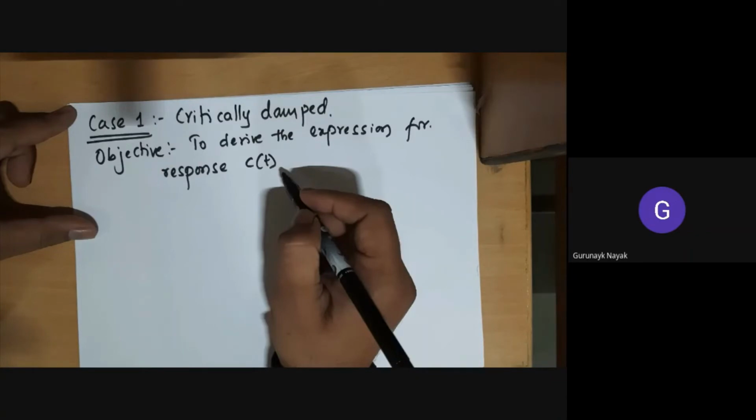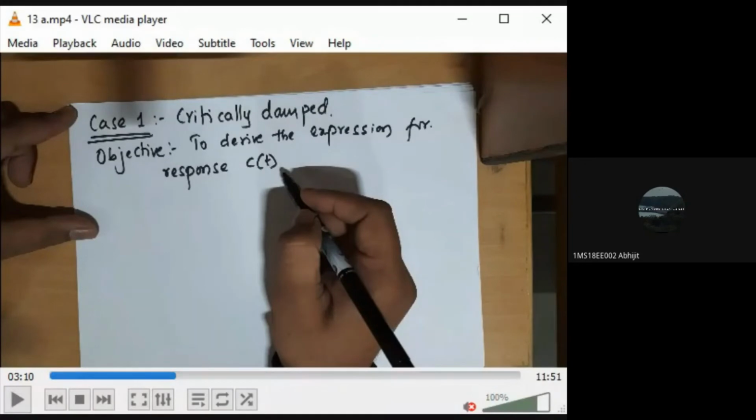Okay, is it fine? Those who raised the query. Sir, then how about the response that you're getting, is it the same, sir? Like zeta equal to 1 and the graph that you made in MATLAB. It didn't give the complex conjugate behavior of the previous example, that kind of oscillating graph, sir. 24 divided by what was that? s square plus 9.78 s plus 24. The graph that you made on MATLAB wasn't oscillating. It just touched 1, whereas the roots are coming as complex. The graph you showed was oscillating until a point and then damping. Why is it happening like this?